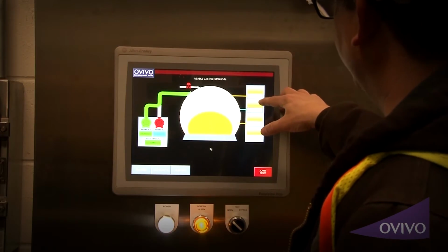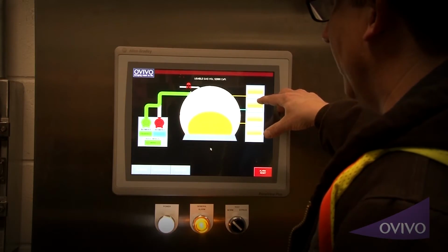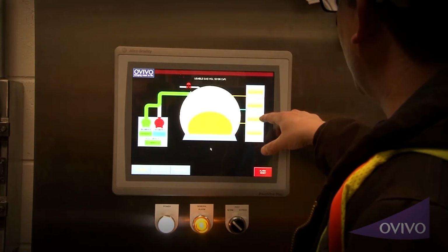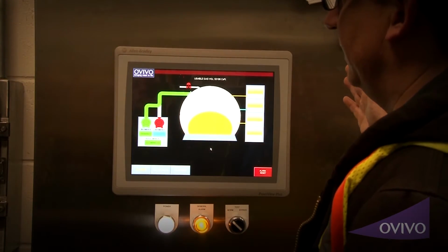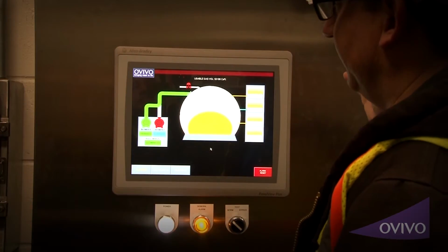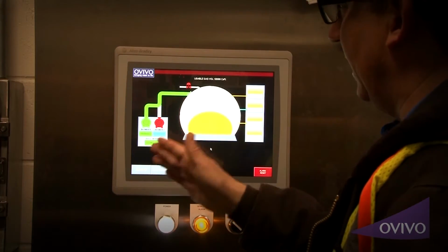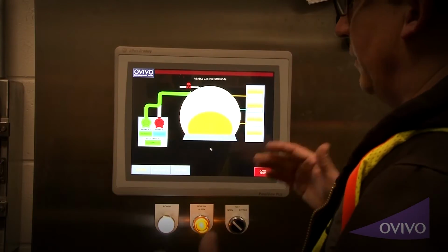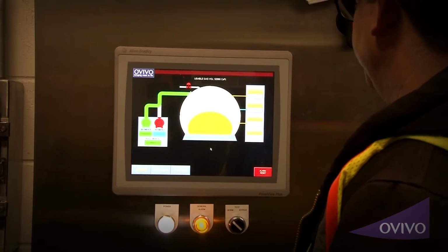And then this air pressure is going to drop down to 1 inch of water column. One fan's going to come on, and then this thing will pump up to 1.5 inches, and then the fan will shut off. And the fan will just keep turning on and shutting off, alternating fans, until something has happened with the gas volume to bring it above 25%.